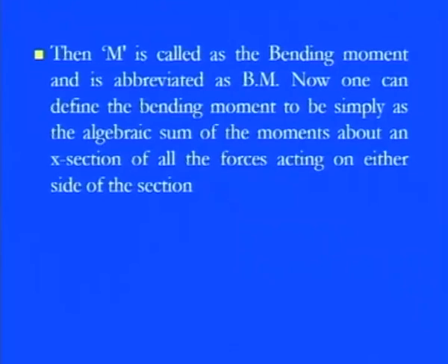So, that is what is termed the bending moment, and now we would like to see, under this force application, whether this bending moment is going in this direction or in this direction. That means in the upward direction or in the downward direction. Accordingly, our main focus will be how this beam will react to this kind of bending moment. And generally we denote this bending moment as M, or we write B.M., which is the usual name of this bending moment.